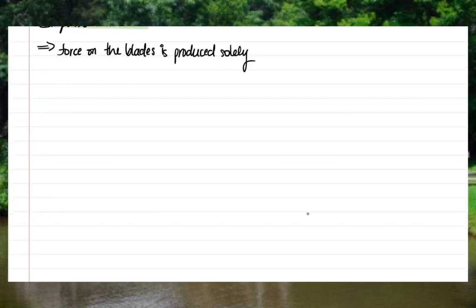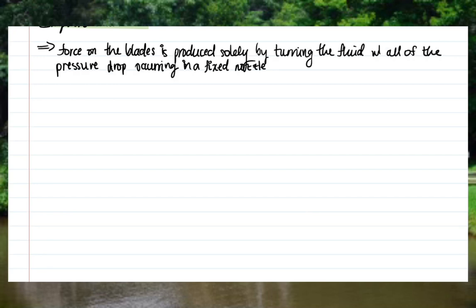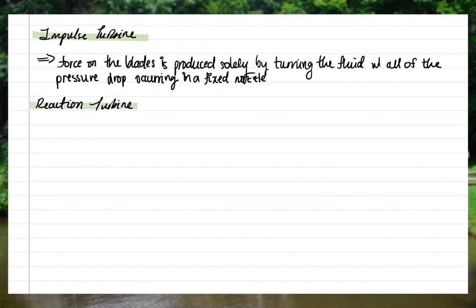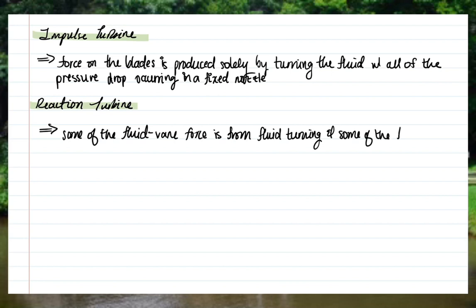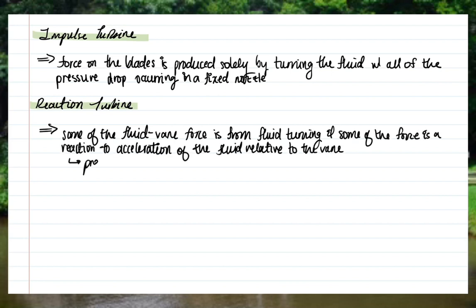Impulse turbines are characterized by the force on the blade being produced solely by the turning fluid, with all of the pressure drop occurring in a fixed nozzle. On the other hand, for reaction turbines, some of the fluid vane force is from fluid turning, and some of the force is a reaction to acceleration of the fluid relative to the vane.